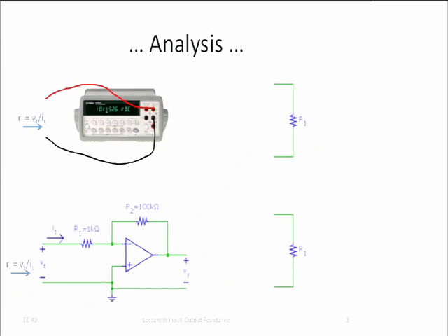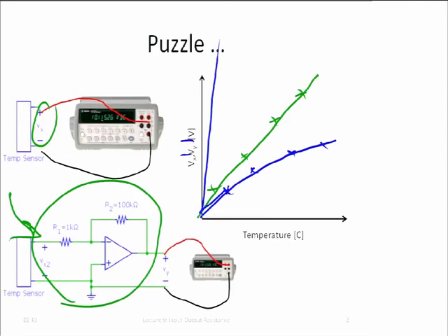What we really assumed here implicitly, and didn't say anything about, was that this current here was zero, right? And here also the current flowing was zero. That's what we really assumed, because of course if there is current flowing also, then that current could produce a voltage drop, and that could precisely lead to the phenomenon that we just observed.